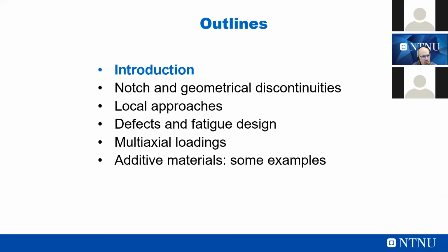So this part of the lecture will have a short introduction. We'll discuss notches and geometrical discontinuities. We'll discuss in detail local approaches, the main approaches that are available, not only the one that I have developed. Then defects and fatigue design, which is very relevant for additive manufactured components, and here I will cite the Murakami approach and also other approaches that are linked to the Kitagawa diagram. I would like to also discuss with you multi-axial loadings, and I will especially stress the importance of a method that is developed by Fatemi Socie. And I want to show you some applications to additive materials, which is the final part of this presentation.